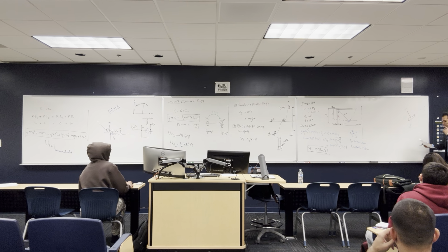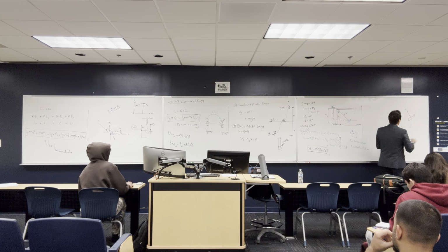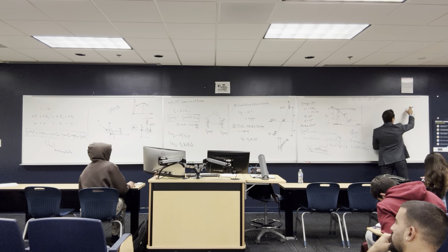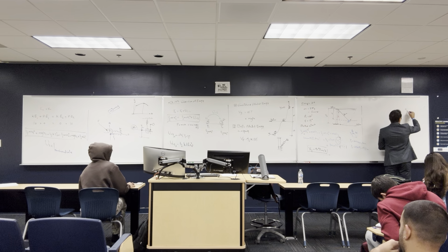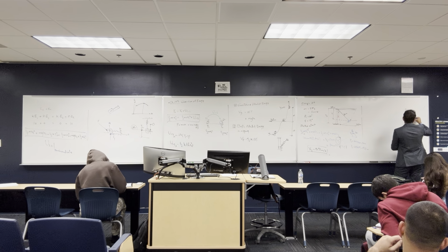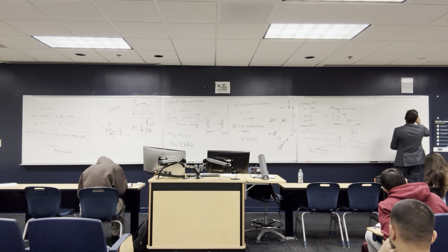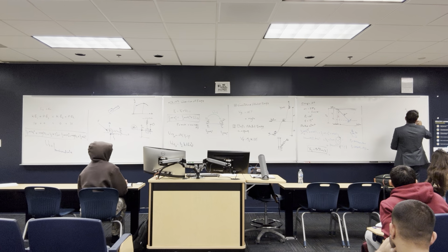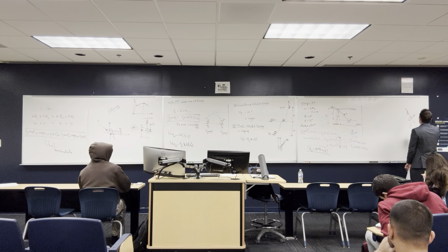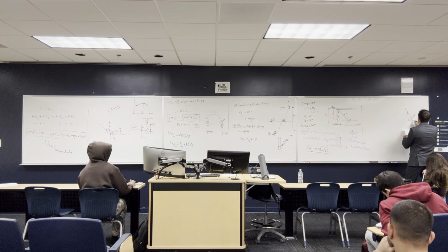All right. So basically, if I want to solve this, this is the free body diagram. At the crash, I'm asking you to find the tension in the cord. At the crash, I know that the angle is 15 degrees. Let's say this is the tangential direction, and the normal is going that way. If I want to find all the forces in the normal direction, I have to find the component of the weight here. So this angle is going to be 15 degrees as well.